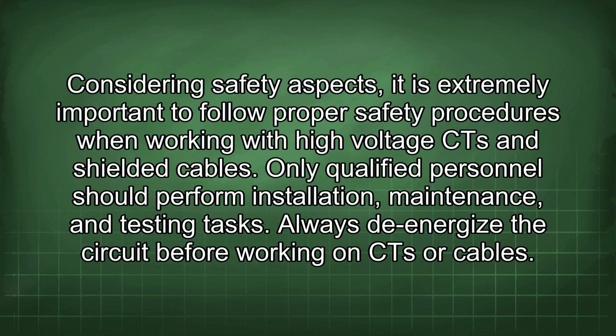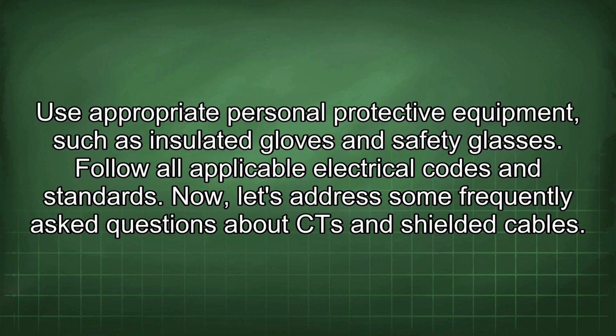Considering safety aspects, it is extremely important to follow proper safety procedures when working with high-voltage CT and shielded cables. Only qualified personnel should perform installation, maintenance, and testing tasks. Always de-energize the circuit before working on CT or cables. Use appropriate personal protective equipment, such as insulated gloves and safety glasses. Follow all applicable electrical codes and standards.